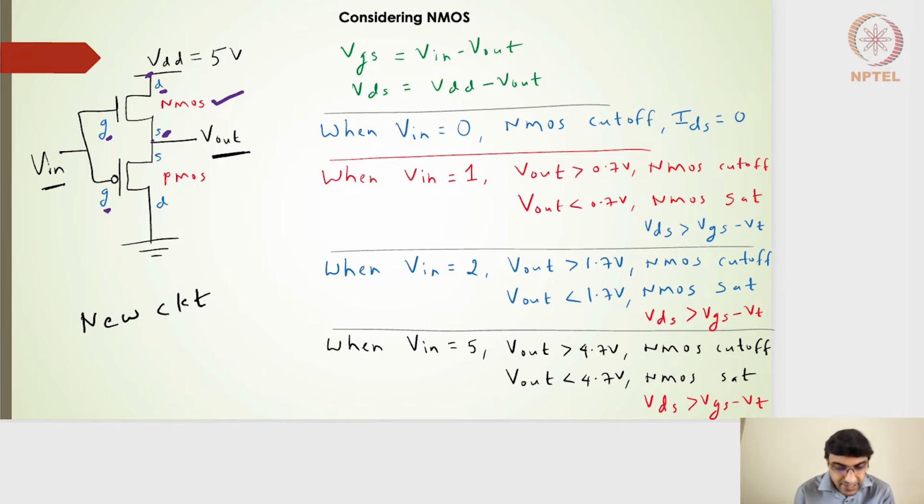On the PMOS side, on this particular PMOS transistor, again we have to choose the source and the drain. Remember that for the PMOS, the source terminal has to be at a higher potential than the drain. One terminal is connected to the ground rail. That means this particular potential will always be 0 volts, similar to what we had seen here.